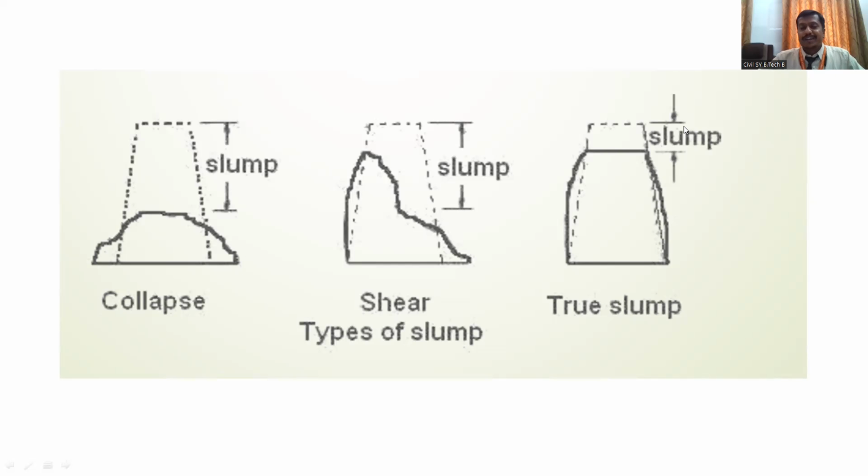Correctly said. When you are going to add excess quantity of the water, more than your requirement, more than the design that you have designed, if you are going to use the excess quantity of water and if you just lift the cone, the concrete will just collapse. It will just spread out throughout the base of that particular cone. So again, you can measure the slump.